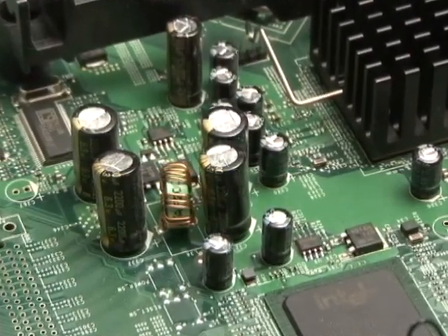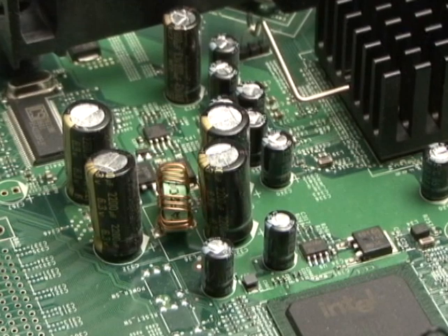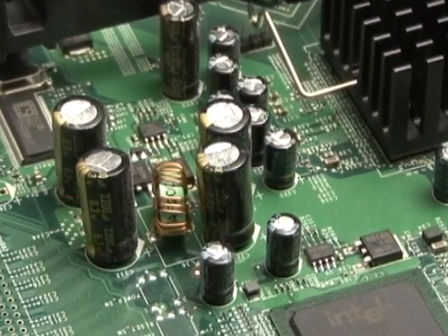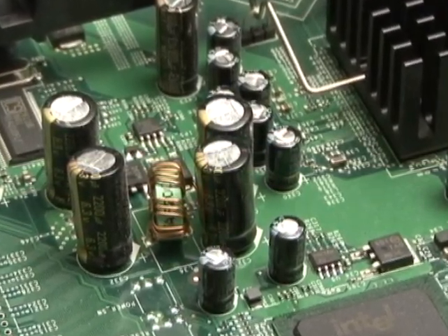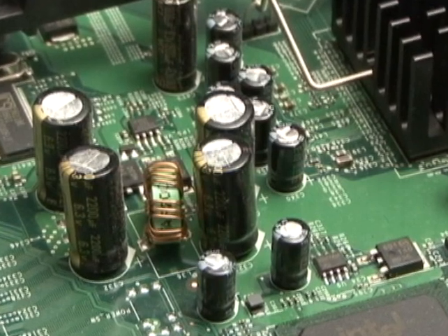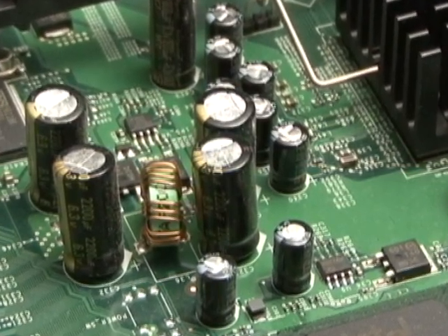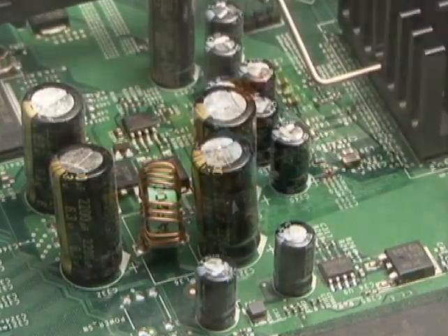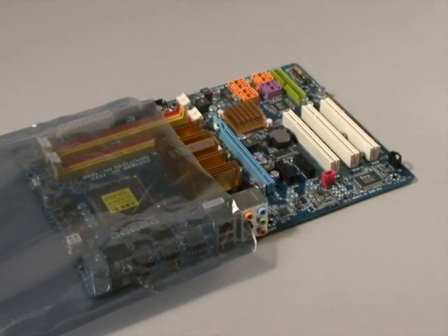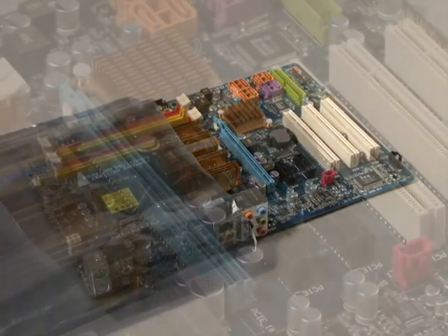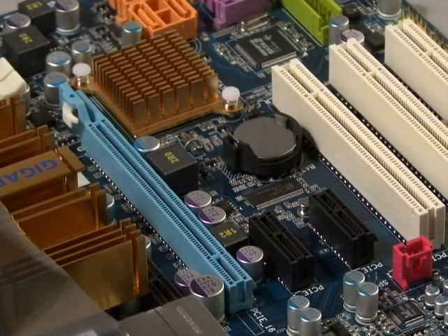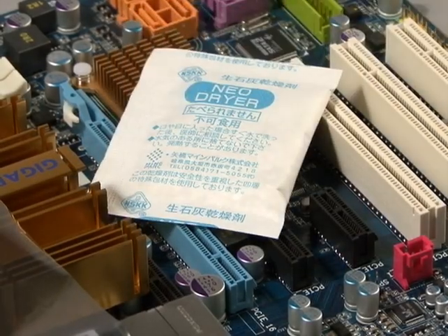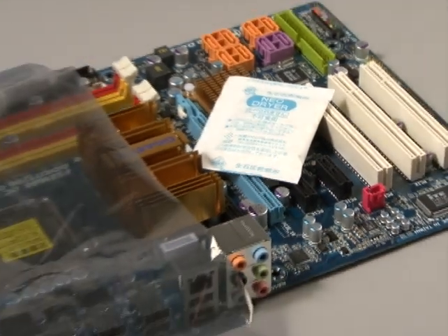On any electronic circuit board, numerous aluminium electrolytic capacitors are used. The lifespan of these electronic circuit boards is generally determined by the lifespan of the aluminium electrolytic capacitors. A spare electronic circuit board is provided on board ships in case the board in use breaks. This spare electronic circuit board must be placed in a cool place to ensure that it can be used over an extended period of time.